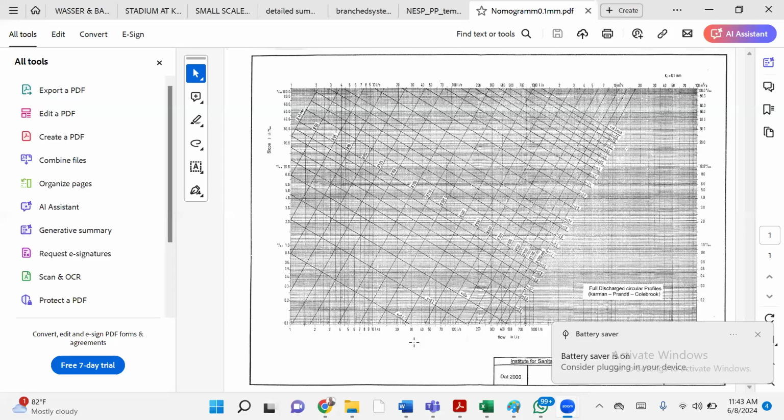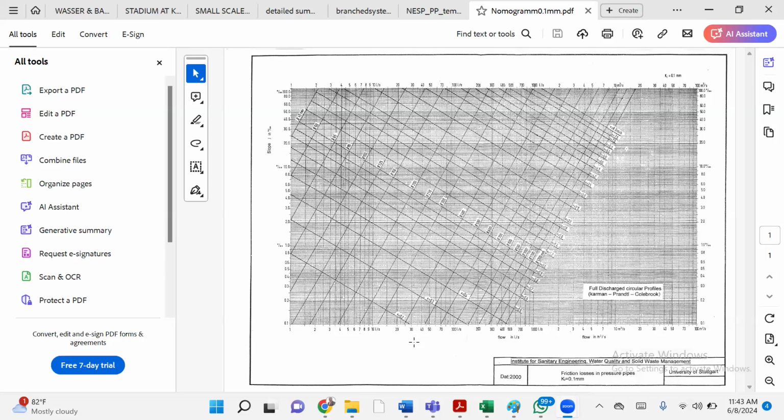So if you are sizing your tank, where do I locate my tank? And how do I know how high the tank should be? You take the elevation of the highest point and the lowest point. If it does not meet your pressure requirement, you elevate the tank to the level that will give you that pressure. If you don't elevate the tank, the water will not flow. And then you also know whether the choice of the elevated place is adequate or not.